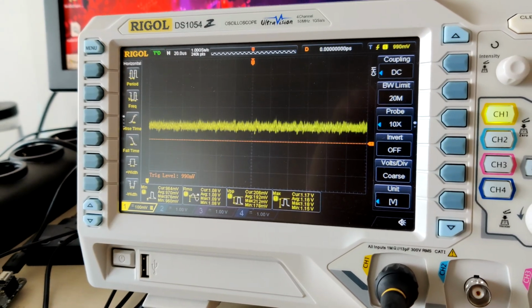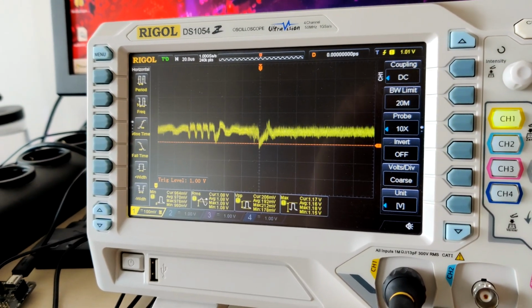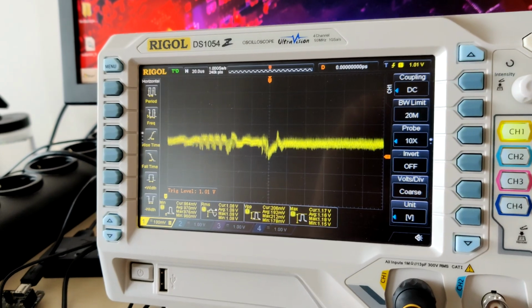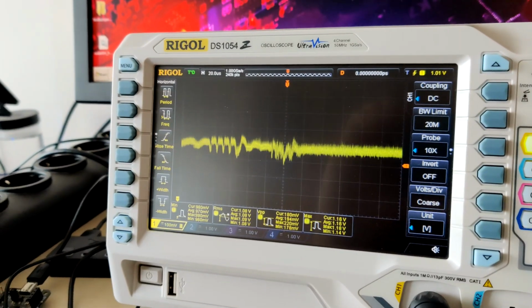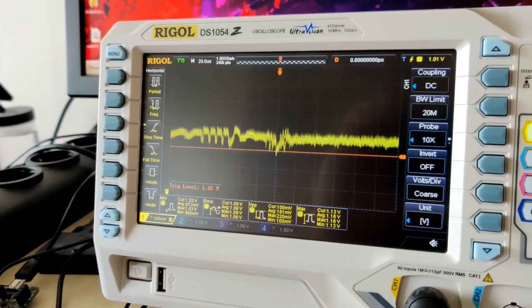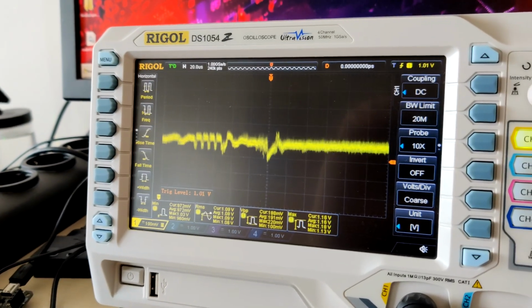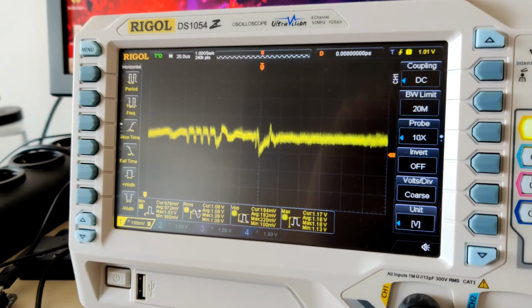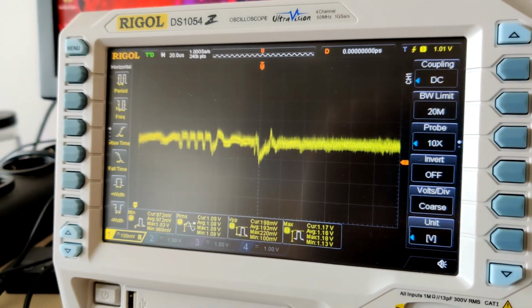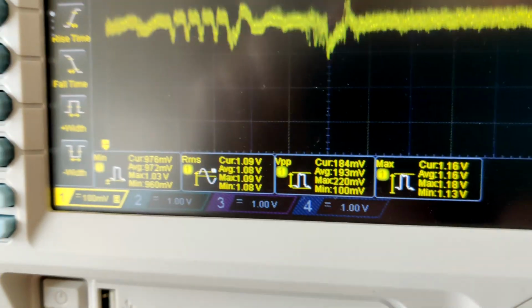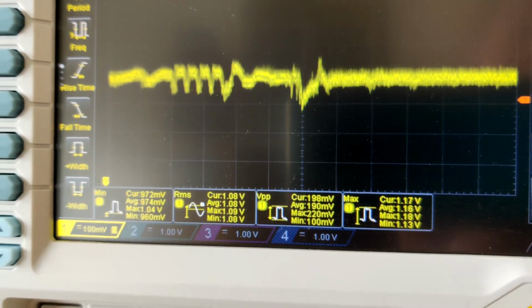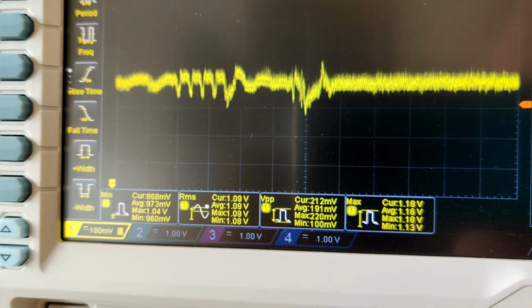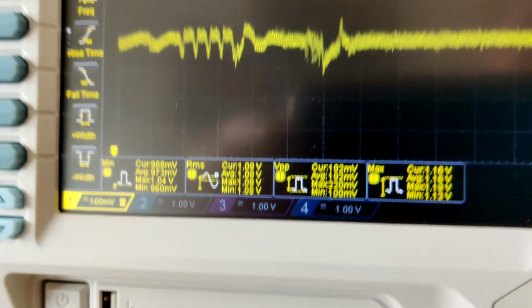And right now our trigger, as you can see, is triggered by a minimum. Every time our voltage drops to that minimum level, and you can see the trigger level is about 1.01 volts, every single time our voltage drops there, we put an image on screen. And this is basically the exact thing that I was trying to show to you on the screen.